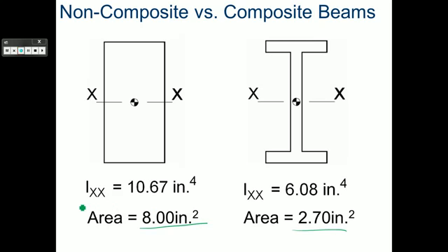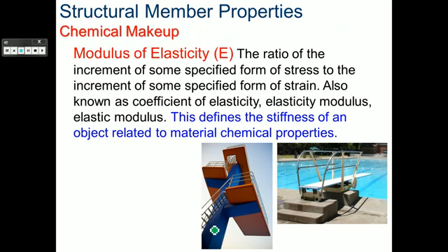But if we look at our moments of inertia, you can see that the block on the right has a much higher number for the amount of surface area. This is why you see I-beams in construction, why you see I-beams in all the skyscrapers. For a much less amount of material, they're able to make something almost as strong. Not to mention it requires less reinforcements because it weighs significantly less.